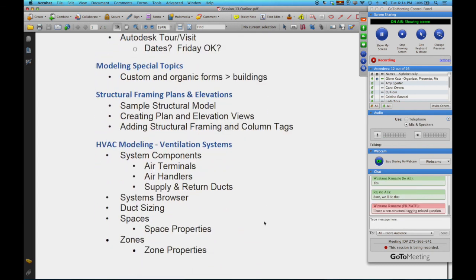For our building design, do you recognize having a core? What if we put a continuous core that goes all over because of the shape of the building? If you don't have a core, okay, typically think about what the core is. The core tends to have to do with two different things. One is providing some kind of lateral reinforcement. A core is useful because it's just a continuous line all the way up and down. It's also usually good for putting elevators or stairs in there.